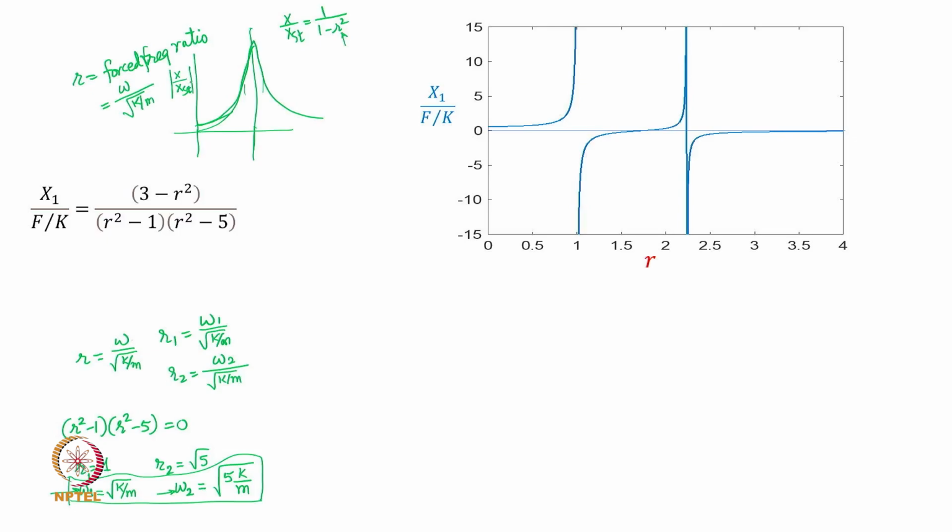So here, because we sketched the variation of the amplitude of this dynamic magnifier with frequency ratio, it was shown almost always like that. Here we are not doing it that way. We are plotting them with their signs as well. There is a reason for that. So I am plotting this as a function of frequency ratio, to see how the response of the compressor is going to look like. So as we expect, it starts with a non-zero value.